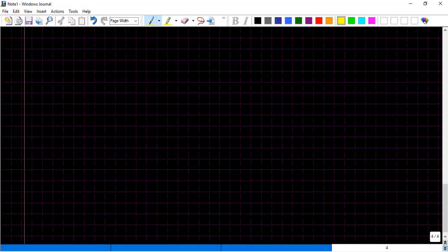One of the major remarks that I want to make here is, in both the cases, to increase the gain, we normally went on to increase the load. Either it could be a resistive load RD, so increasing the resistive load would increase the gain, or in the second case, we know that the gain expression for a diode connected load can be written as gm1 divided by gm2, and in order to increase this gm1, we could either play with the W by L factor, or the other case is with respect to VOV. But in all these cases, the swing is getting disturbed.